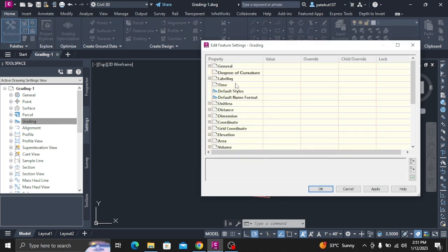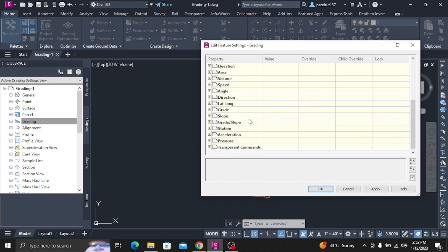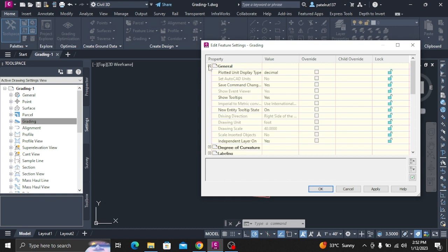Expand the Grading Criteria Sets collection. The Grading Criteria Sets collection displays the existing grading sets for the drawing. You will create a new grading criteria set, then create two new criteria within the new set. Right-click Grading Criteria Sets. Click New. In the Grading Criteria Set Properties dialog box, enter Ditch Criteria Set in the name field, and optionally enter a description. Click OK. The new criteria set is displayed in the Grading Criteria Sets collection.